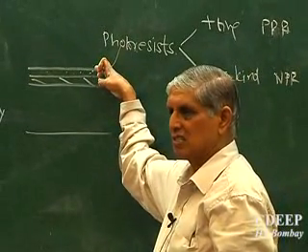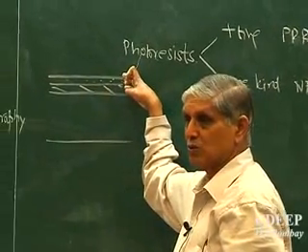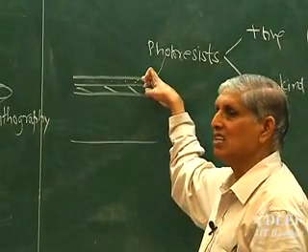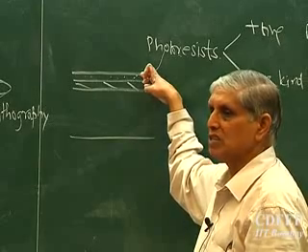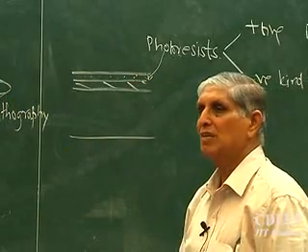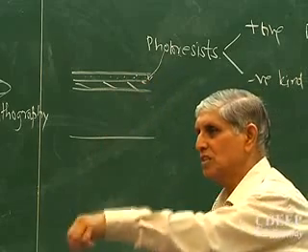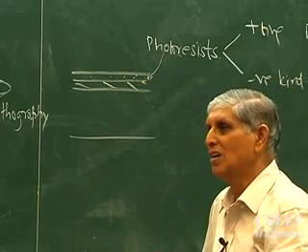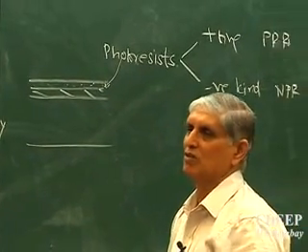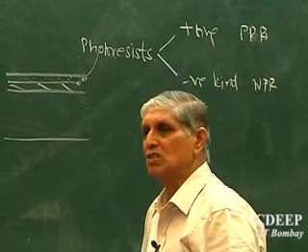Let's say this resist is NPR. NPR has a property: the polymer, which is what your resist is, has carbon chains. Right now this resist is essentially open chain, that is, all carbon hydrogen chains are open. So what does that mean in chemistry? If there is an open chain structure and I put this resin in some solvent, will it dissolve? Yes, because all bonds are available to dissolve. Reactions will be very fast on them. So all open chain carbon systems will dissolve fast.